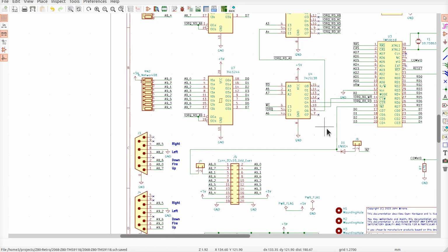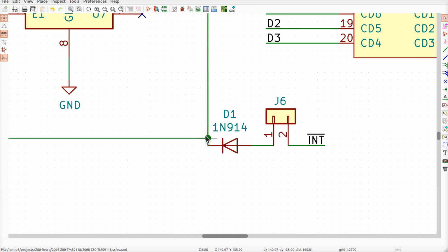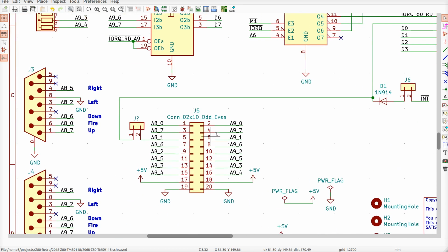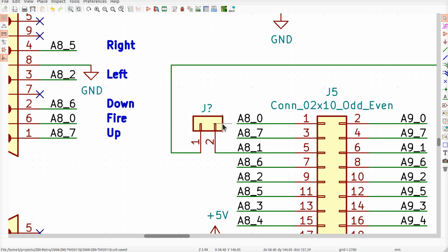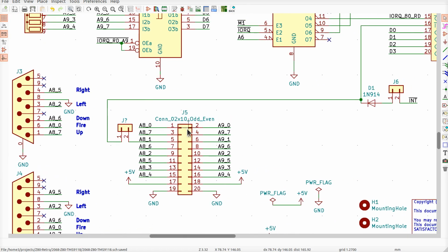Back to the interrupt signal, exactly as I've done on my board. Now, if you have that pull-up resistor on it or not, it's only 10K. It's not going to mess with this signal that much. If at all, it really won't have any impact. I'm not going to worry about that one hill of beans, okay?